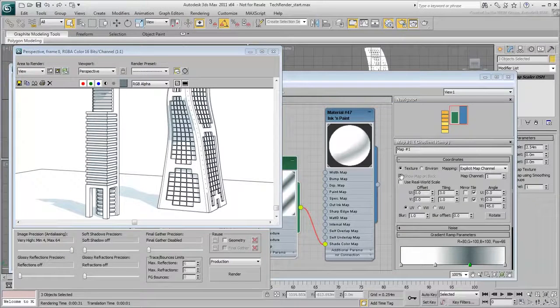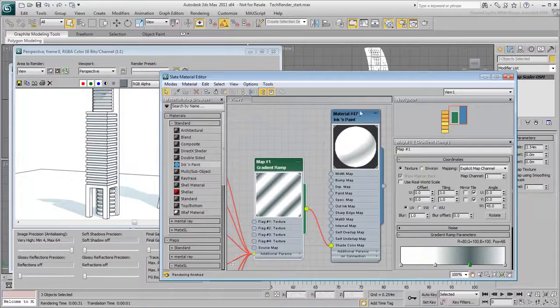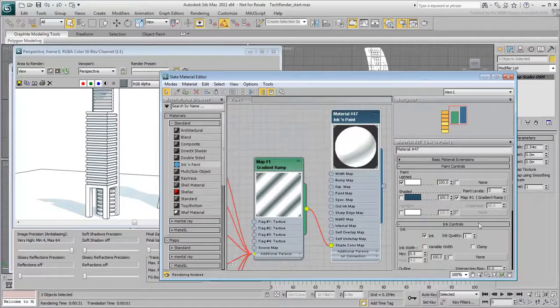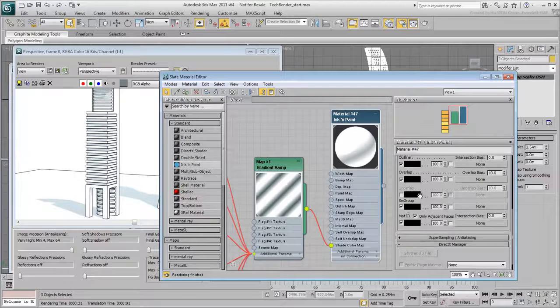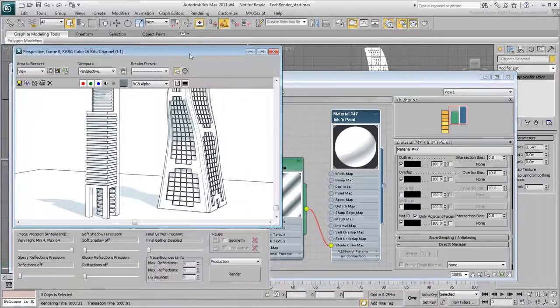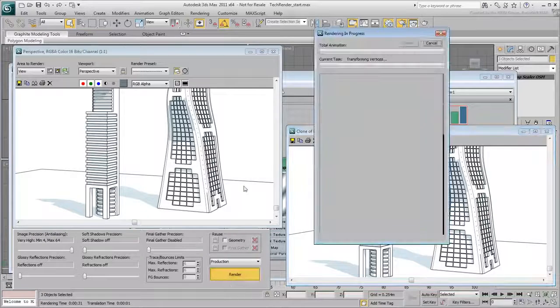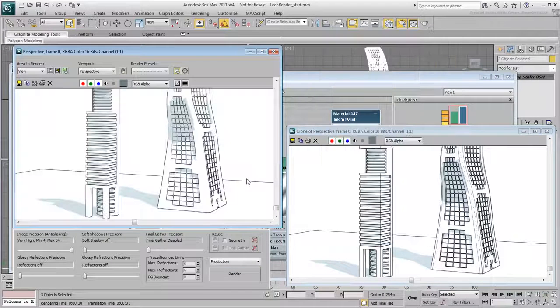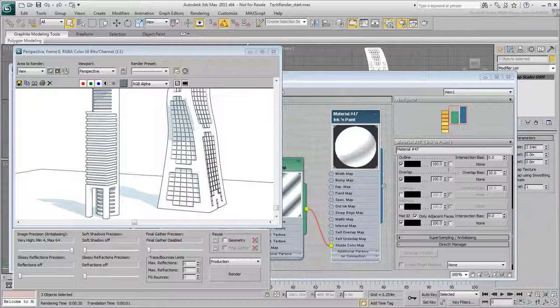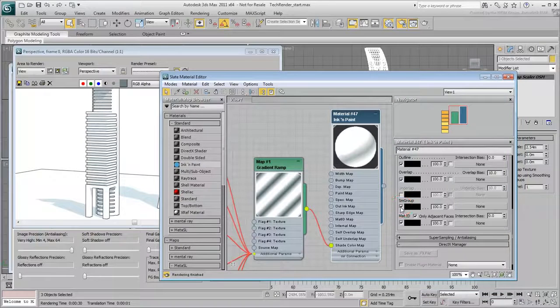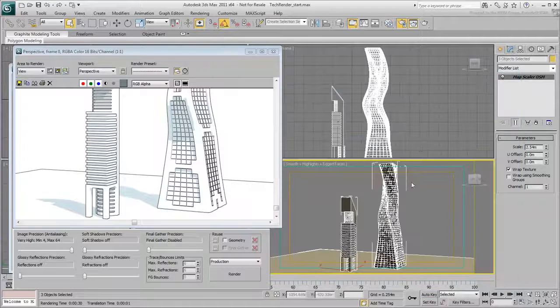These are happening because some of the polygons on the rounded corners happen to have multiple smoothing groups. One way to fix this is to disable smoothing groups from the ink properties of the material. However, this is global to the whole scene and will remove ink strokes that you actually want to have. A better solution is to adjust the smoothing groups on the building corners. Restore the smoothing groups option of the ink and paint material.